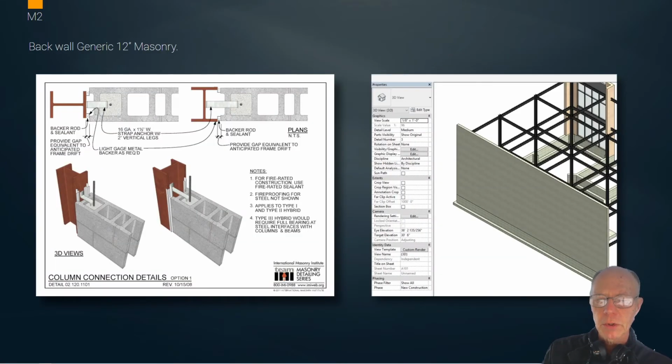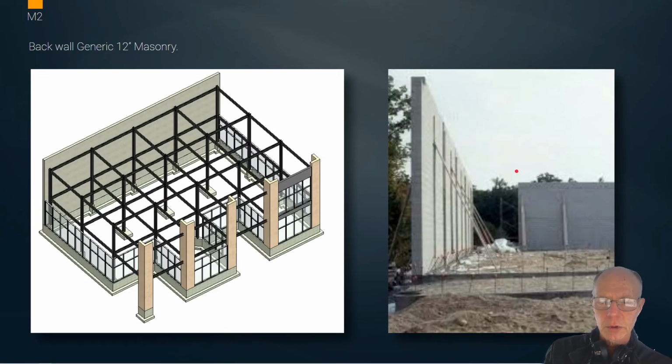One of the last components that we're going to do in M2 is to construct the back wall. Excuse me, yes, it's M2 of CMUs, concrete masonry units. And so I wanted to show you the details about those, just some visualization. So these are typically 8-inch deep blocks. They're in a staggered arrangement. These are some details of the attachments of them when they're in an engaged I-beam situation. In our case, we put the I-beam on the inside of the wall, so it's a little bit different.